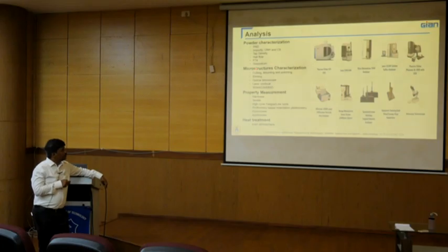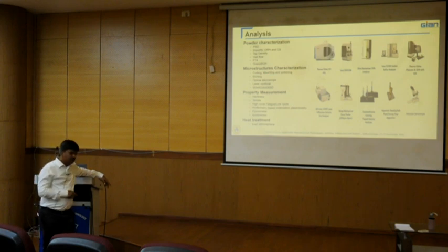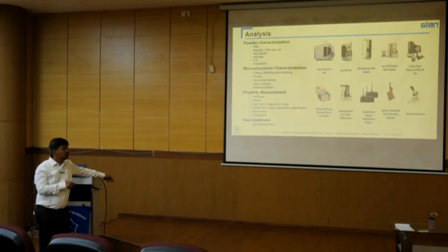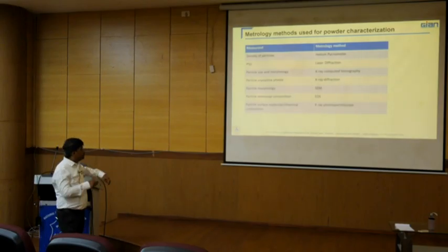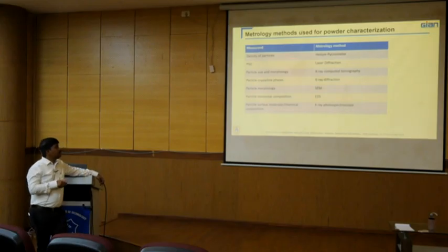With microstructure we can use SEM, mechanical etching, optical microscopes, or confocal microscopes. And for property measurements, there are hardness, tensile, high cycle fatigue, profilometry, indentation, pycnometry or Archimedes; all these are the properties. And even we can go with the heat treatment aspects. We use all these techniques to qualify our powder particles. We can even analyze the hardness of your powders. The morphology and characterization of the powders are very important.